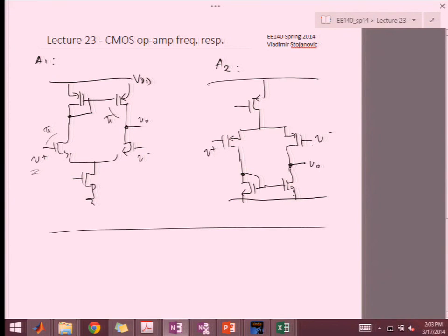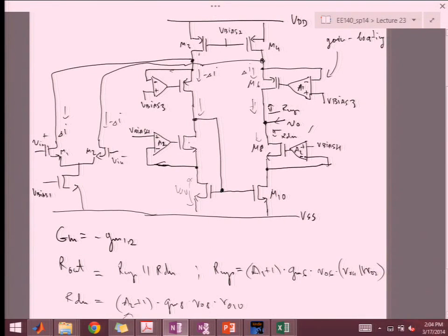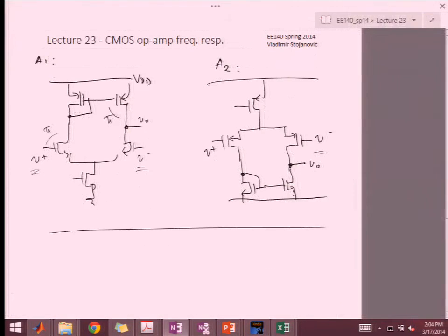So one of these has to connect to what? Take a look at the previous. One connection is the source. Another connection is this, right? These two better be very close, otherwise you're completely saturating. This is not small signal, right? So assume this is a reasonable gain. V bias has to actually be very close to this voltage, right? So then V bias has to be very closely related to VOV plus VTH and that kind of business, right? And one is lower, another one is pretty high, which means that if you go back to this, one of these ports is really, let's say, in our case, V plus was really high or really low, right? So if V plus is really high, then you want this topology over here, because in this case,